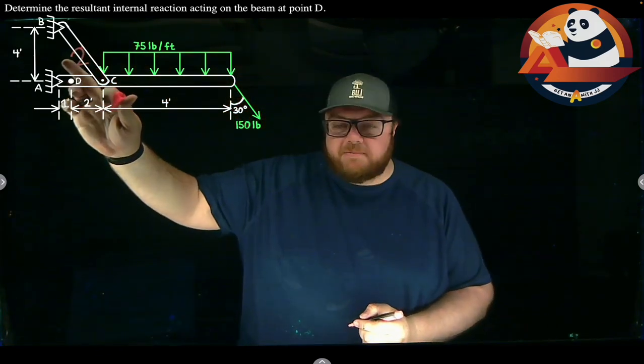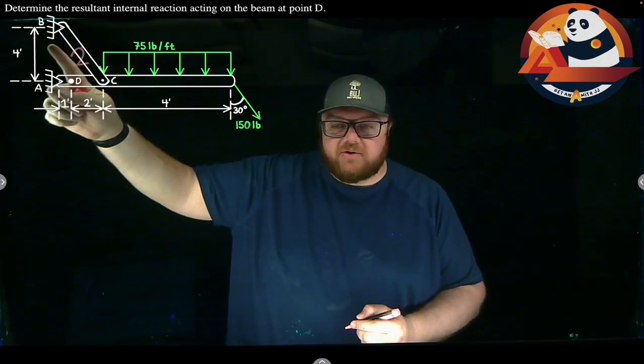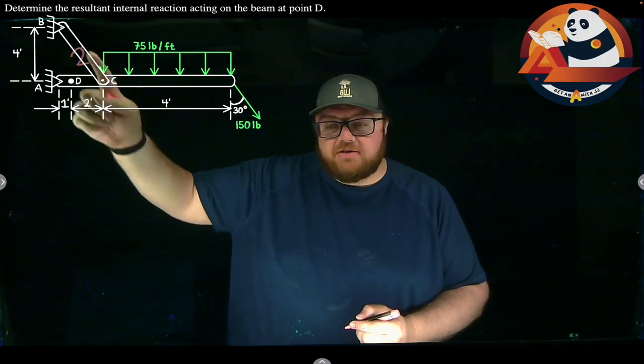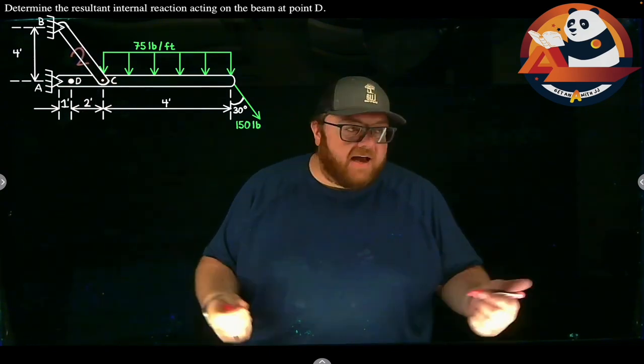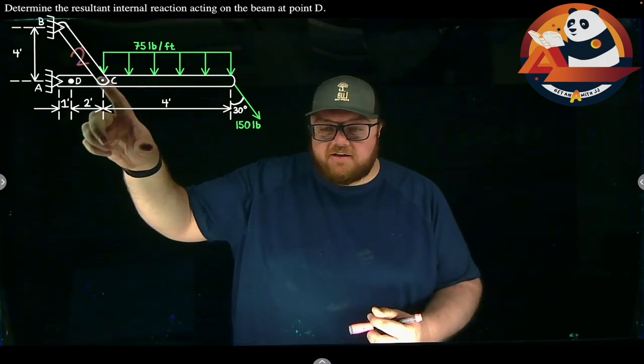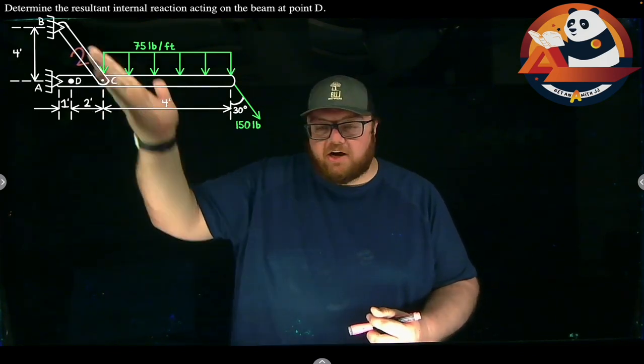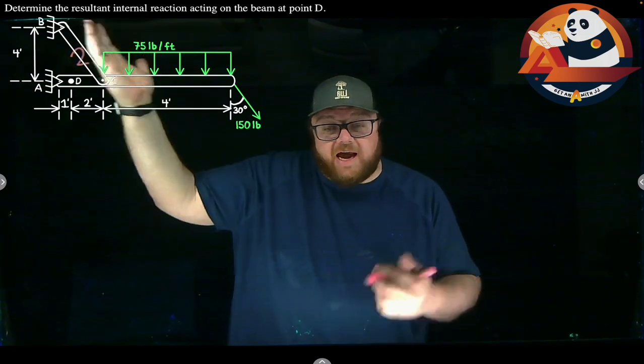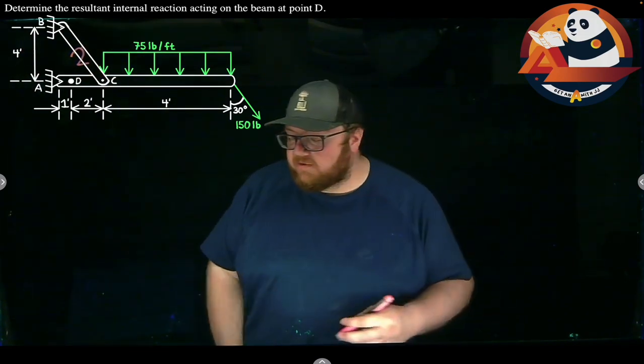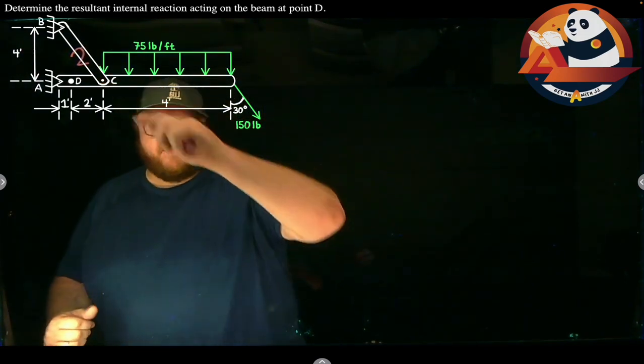If this is a two-force member, then I only have one force on this. It should act in a straight line from B to C, or else from C to B. I can guess that. The math will let me know which is right. Really, I'm taking the resultant of CX and CY here and resolving it down to just one force. It just has to go along that member for it to be in equilibrium. So we're able to come in and simplify our work some.